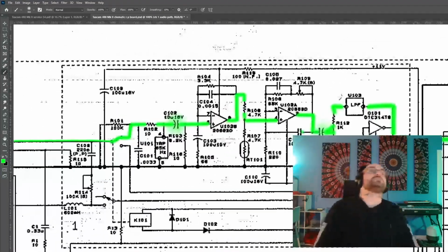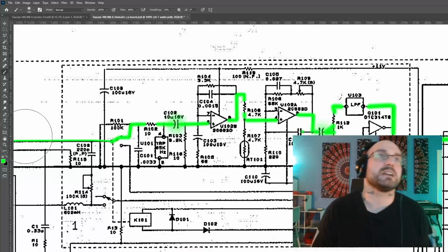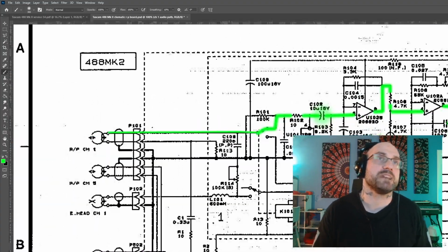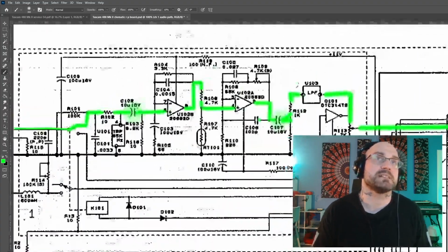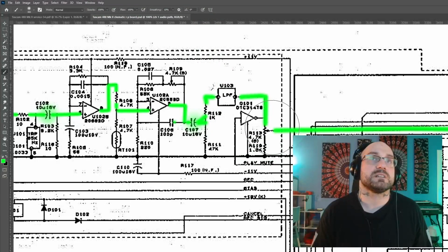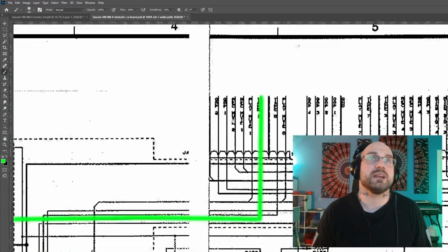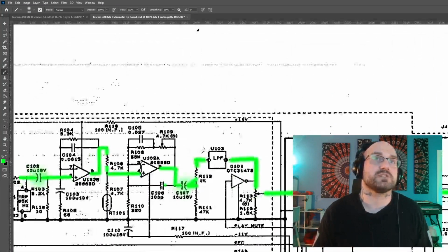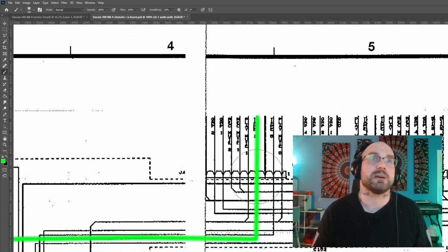And in fact, I could do a faster thing where I make sure that it's at least getting into this relay, to make sure that there isn't a problem with the connecting cables coming from the head into the system. But then test this resistor, because if it's okay there, then I already know that I shouldn't be troubleshooting this board. I need to see what's happening about how it comes out of this board and into the rest